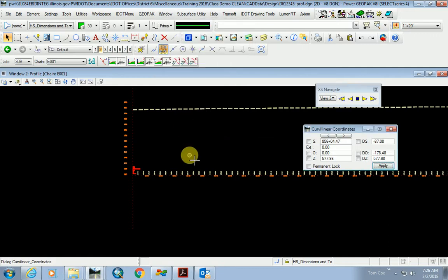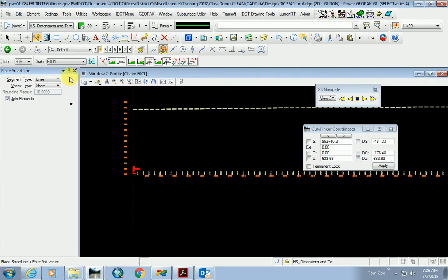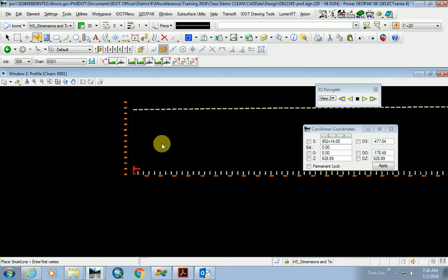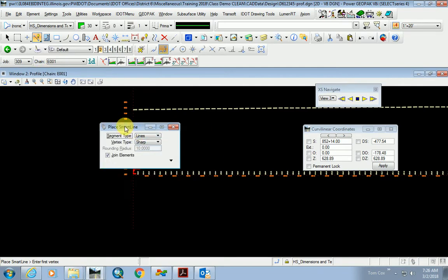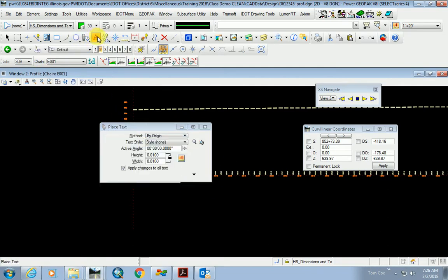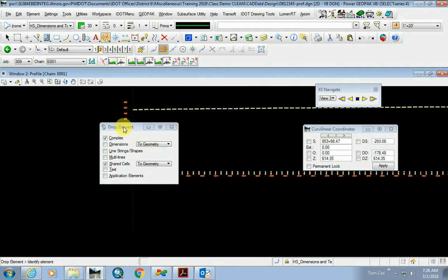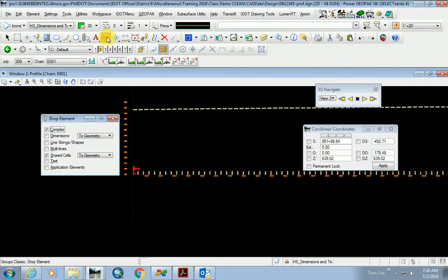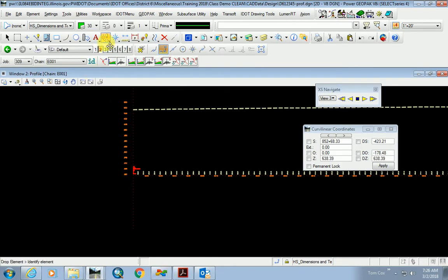That's one way. Sometimes it won't even be listed there for some reason. So another little trick, maybe not on that one, but a lot of other MicroStation ones, like this dialog here, how it changes when I'm in different commands. Let's say you're trying to get this drop element and it's hidden somewhere and you keep hitting it and you can't get it back.